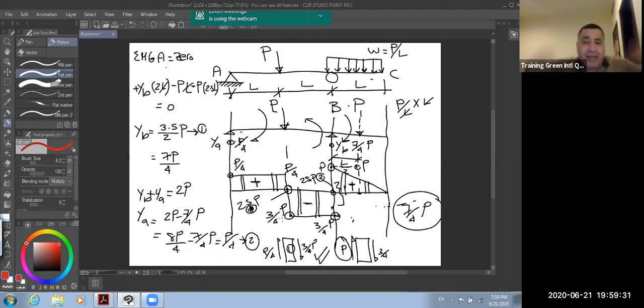The section is under deformation. So the influence line of the section goes up and down, and we need to know where exactly the maximum shear force is. We are going to take this maximum shear force and give it to the designer: please design the section for me. Okay, clear? Very good.